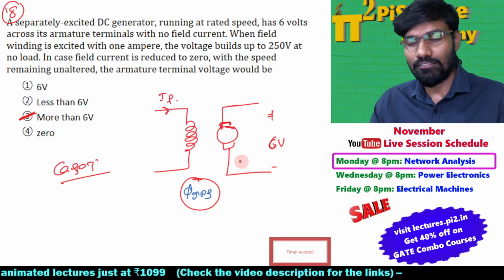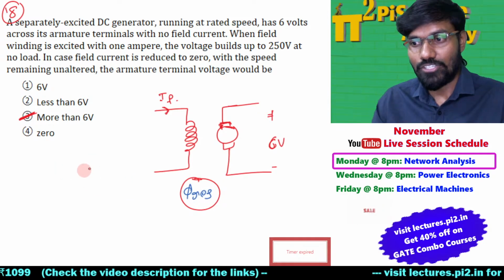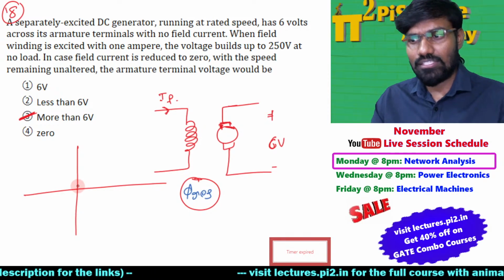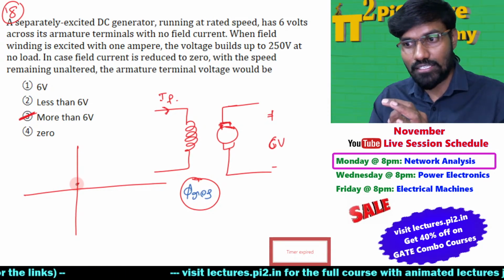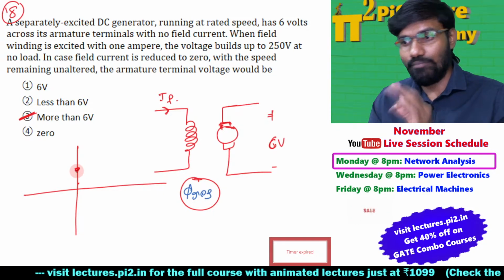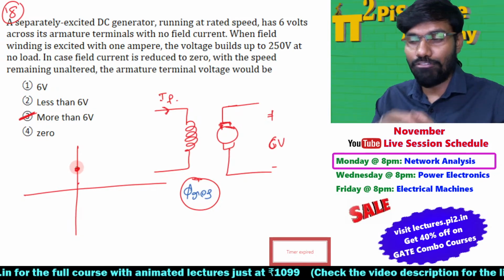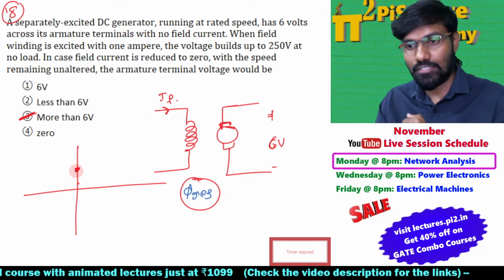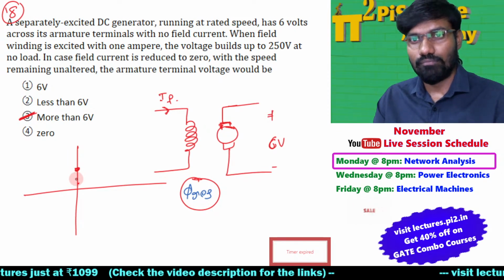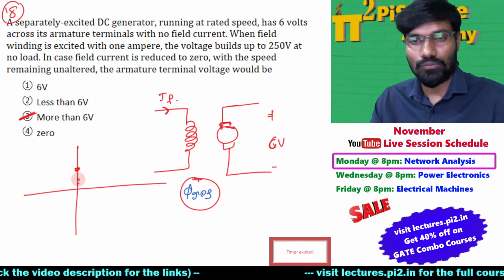Yeah, partly Gautam was correct. It's due to the hysteresis effect. If you see, at the beginning we have some residual flux. Now after some time, maybe after 10 days, after maybe 20 days, what will happen to the residual flux? Residual flux is slowly coming down, because residual flux will not be there for lifelong. Residual flux will come down.